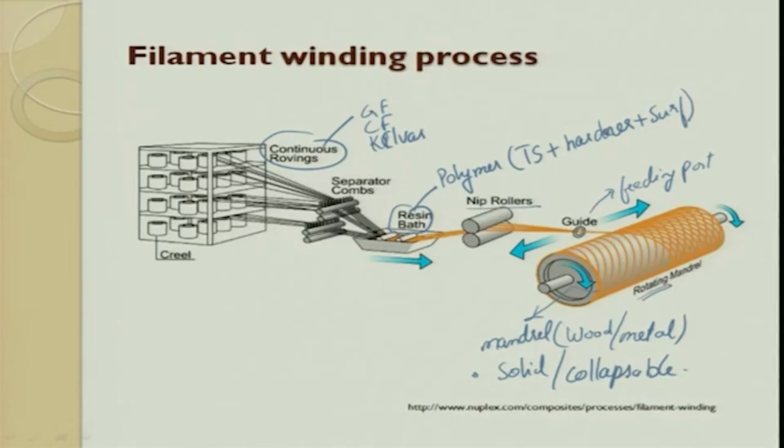Now what happens, as and when you increase the glass fiber roving on top of this mandrel, the thickness increases. Here, depending upon the feed rate, depending upon the RPM, you can have varying hatch patterns. These hatch patterns can be process controlled to get whatever you want.